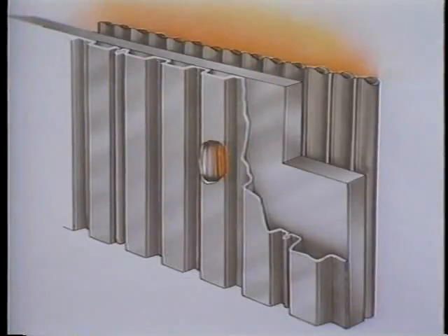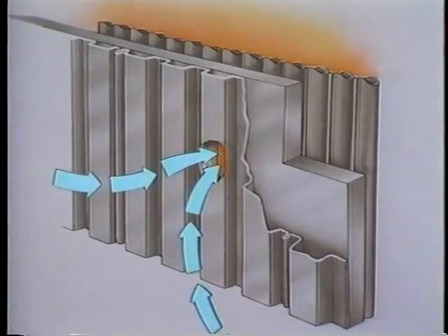In most cases, the choice of action will involve isolating the leak and continuing to operate until maintenance can be scheduled. Or, if the leak is severe enough or endangers the boiler flame, shutting the boiler down. Once in a great while, a leak will develop in the boiler casing. The severity of the leak and the design of the boiler will determine the action taken by the operator. Balanced draft boilers, for example, operate under a slight negative pressure. For the most part, any leak in the casing will draw air into the boiler.